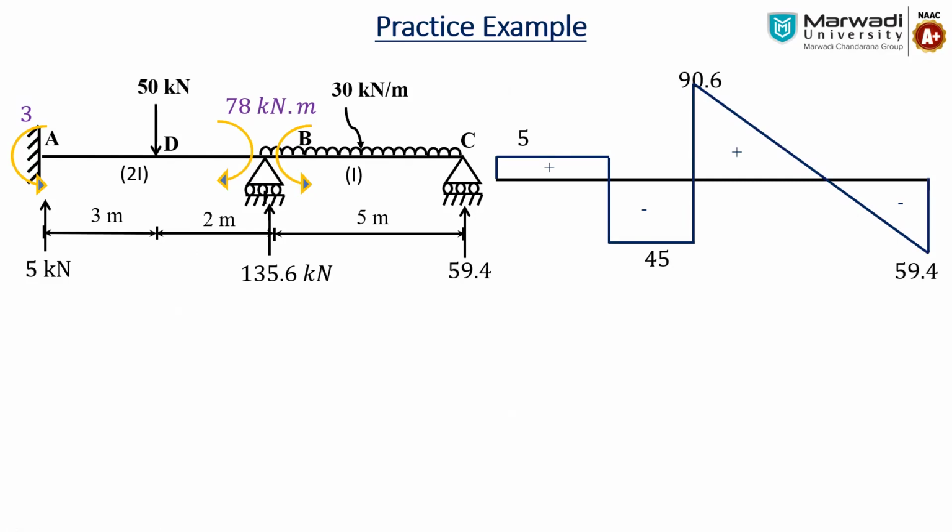At which point is the shear force 0? At that point, we will get the maximum bending moment. You can use the similar triangle method, or there are other shortcut methods. You can find out that point, and that is 1.98 meter. With respect to that, there are two ways of drawing the bending moment diagram. The first way is to show the net diagram.